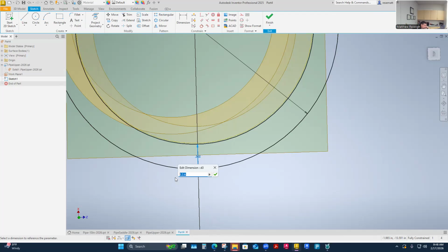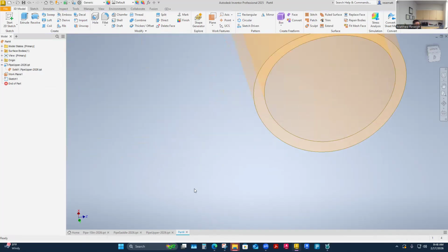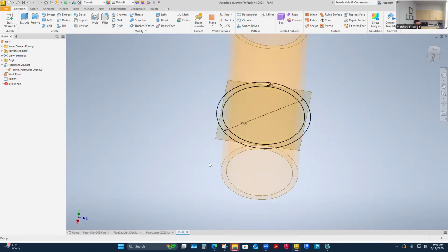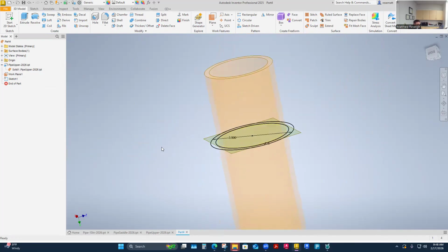But so I'm going to go back to the 0.216, which was the schedule 40 wall thickness, with a bigger gap. So I'm going to say finish that. And so I'm saying I'm using schedule 40. It's easy to change though. This is just the sketch I would come into. It's only going to affect the ID of that, and it would affect my description.